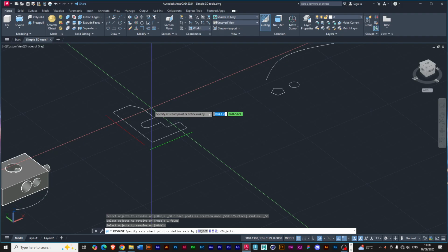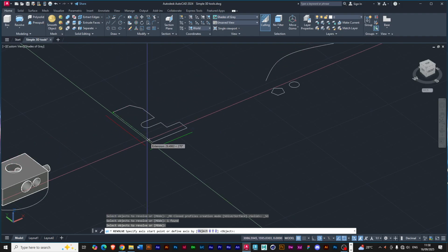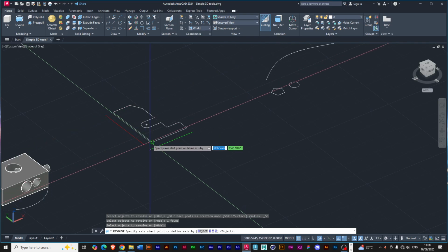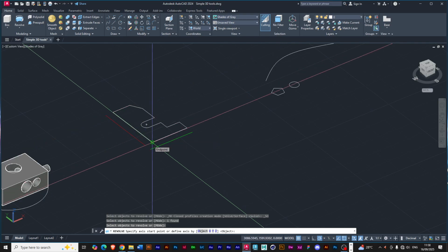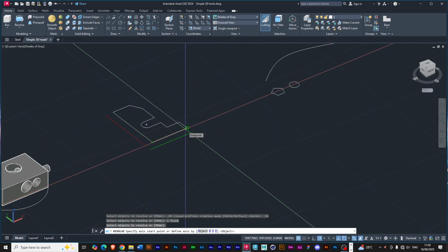You can revolve it around itself, just like we did in Illustrator that time. You draw a bottle's outline profile, and then that middle point, it will revolve around it. Then you can offset it. The same thing here. So you can revolve it around itself by specifying the end point. If I click here and click here, it's going to revolve around that line. If I click here and click here, it's going to revolve around that point.